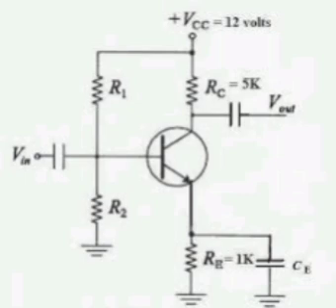For AC analysis, the common source amplifier or MOSFET where gate is shorted to drain can be written as an equivalent resistance R equivalent equal to 1 by gm2. gm2 equal to μn Cox W by L into VGS minus VT, that equal to 1.1625 millimhos. R equivalent equal to 1 by gm2 that equal to 860.2 ohms, that equal to 0.86 kilo ohms. gm for BJT, gm1 equal to IC by VT that equal to 2.325 milliamps by 25 millivolts. These all come under AC analysis. gm1 equal to 93 millimhos.